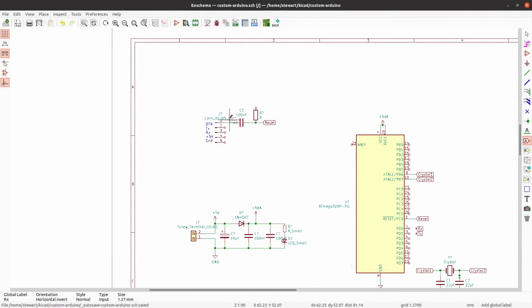And we can copy these. And then wire them up. Now, if it looks odd that transmit goes to receive and receive goes to transmit, then that's how serial UART connections work. That the transmit of one goes to the receive of the other.